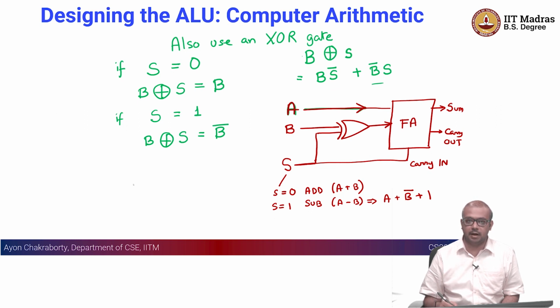And the subtraction operation basically needs a representation for expressing an integer x in its negative form, right. So, if we have a number a, and we are doing a minus x, that is nothing but adding minus x to a, right. So, we need a representation of negative of x, which is the way we do it using a 2's complement. This is the name that we have given to that, and we have discussed in detail how this is mathematically feasible, and we saw that it is actually x complement plus 1, right.